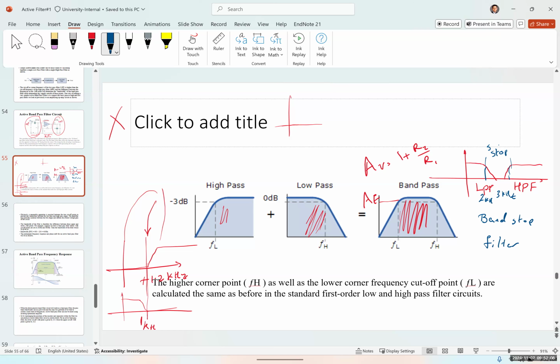There's a lot of applications for this, especially in communication systems, when you want to block noise in a certain frequency. It's very good when you have a fixed frequency, not a variable frequency. This is not going to work well with that. So for example, for these power outlets, we know that the frequency is fixed at 60 hertz. So you can just put a band stop filter at 60 hertz, and it's going to block everything around it, for example, between 58 and 62 hertz. So there's a lot of application, especially for noise canceling.